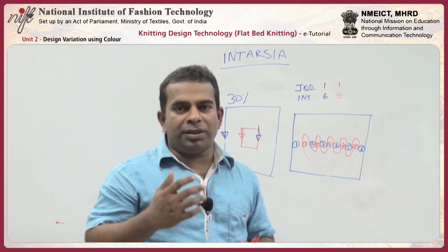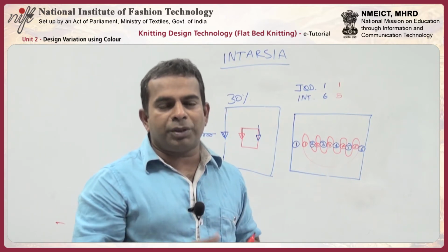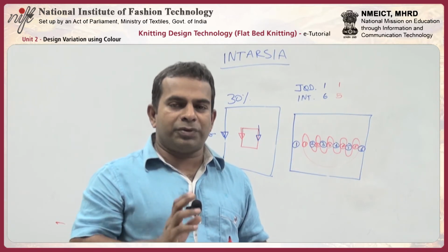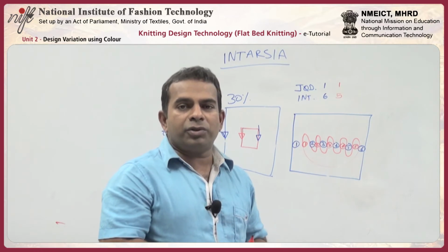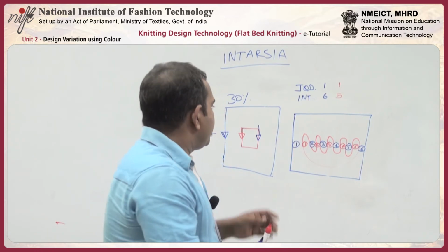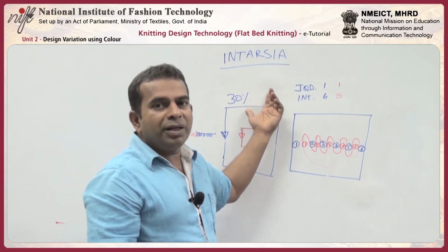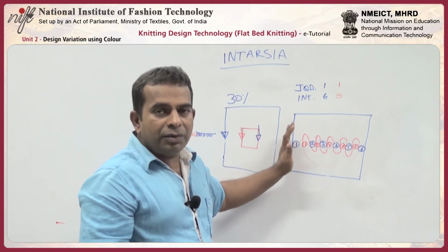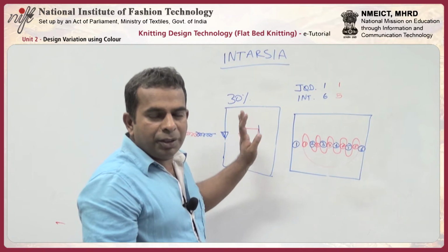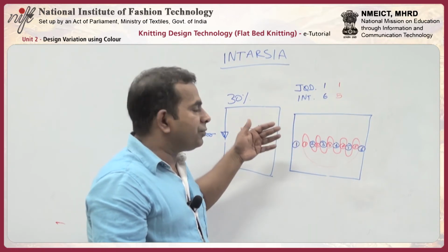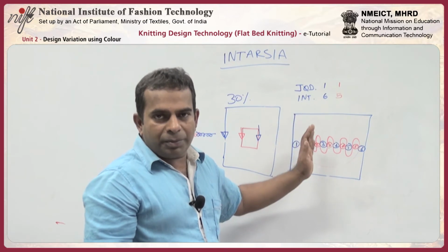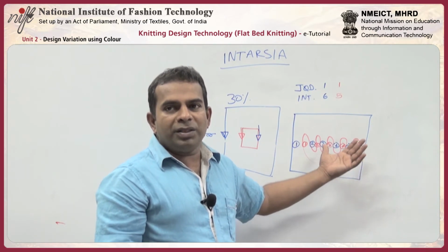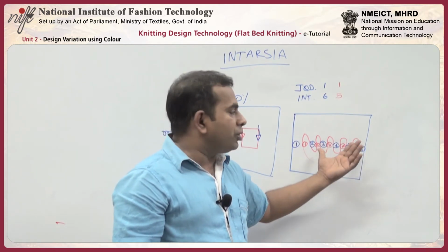Let us say a different fabric, different yarn has been used, like cashmere wool. Cashmere wool is very expensive, one of the most expensive fabric used for knitting. It will cost close to 20,000 rupees a kg. So 30% wastage would mean thousands of rupees. Now, if we are using cashmere, we will never try to do a Jacquard design because there is a lot of wastage, a lot of yarn floating behind, creating excess fabric, and all that can be saved if you use Intarsia design. But with Intarsia design, your knitting cost will go high.